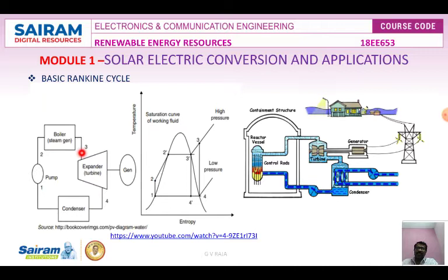More heat is added to superheat the saturated vapor at constant pressure. The temperature rises, and the superheated vapor enters the turbine and expands in an adiabatic reversible process to the low pressure maintained in the condenser at state 4.